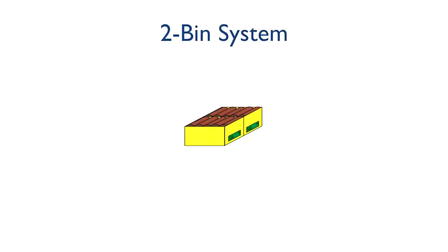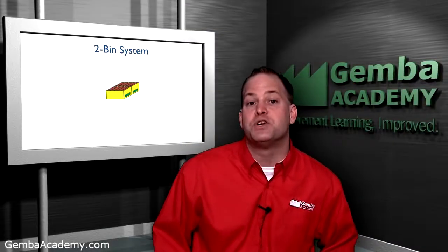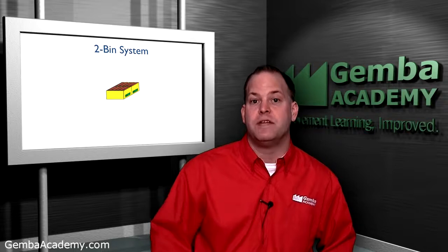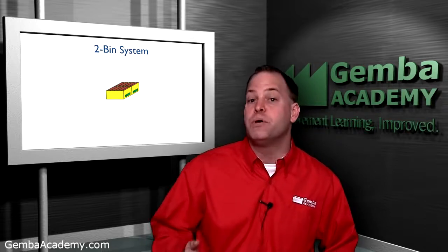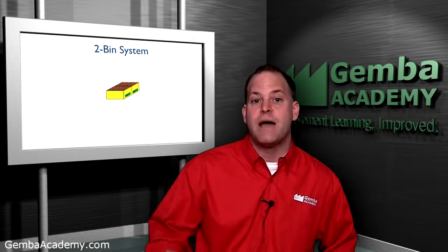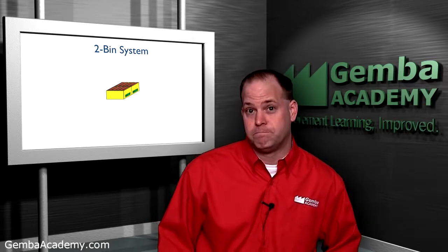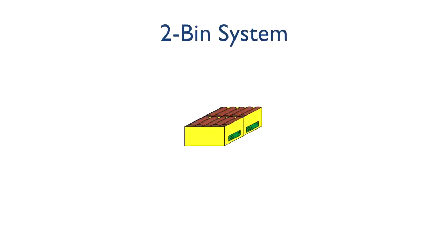Now, another system that doesn't rely on traditional Kanban cards is the two-bin system. In the two-bin system, standardized bins or containers perform the role of the Kanban card. An empty bin signals that more parts are required. The collection of empty bins should follow time-based standard work whenever possible so that one person can supply the materials reliably for a department or section. Now, here's an example of how a two-bin system works.